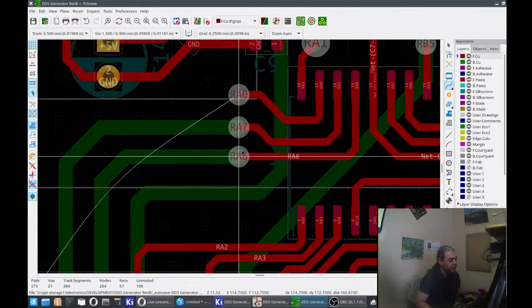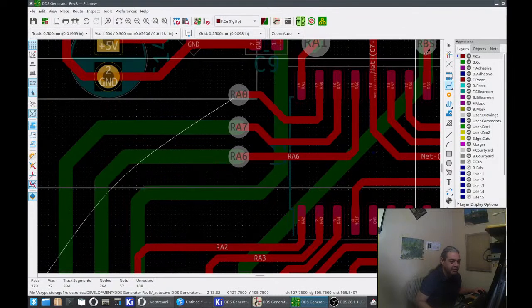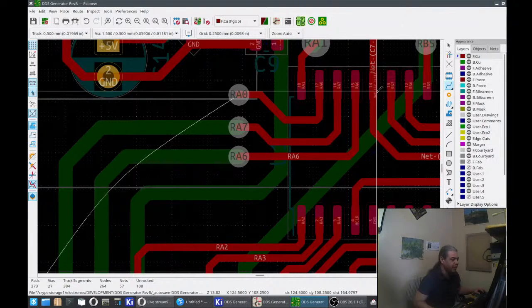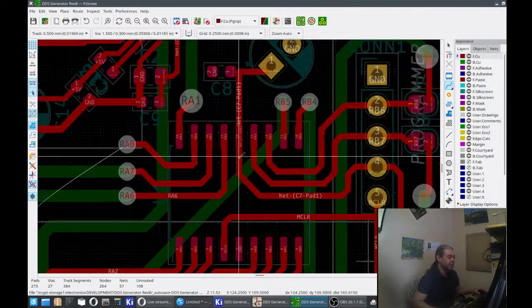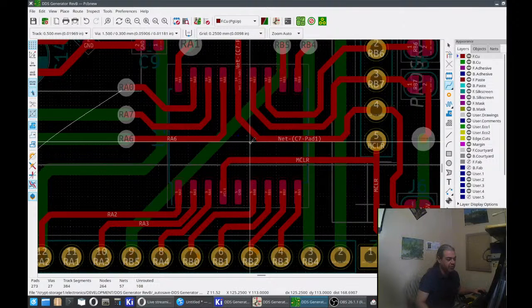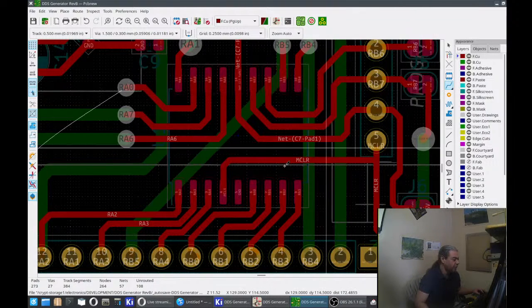Oh, I think it was just a via to get them breaking out, because I didn't know how I was going to get those traces out. So I think by default, by instinct, every trace coming out gets a via, and then I can work on something else. So that there's a starting point, or at least a breakout point for every component.